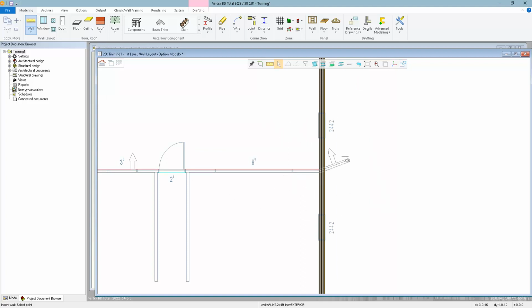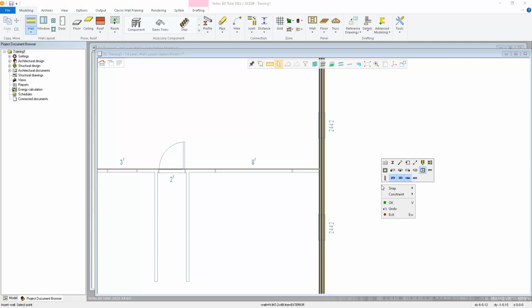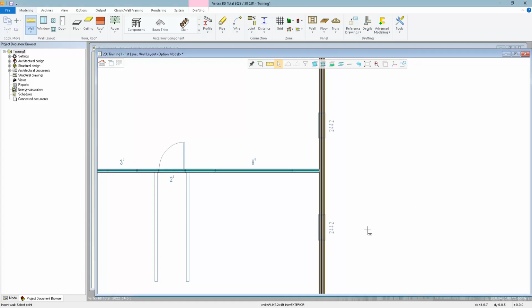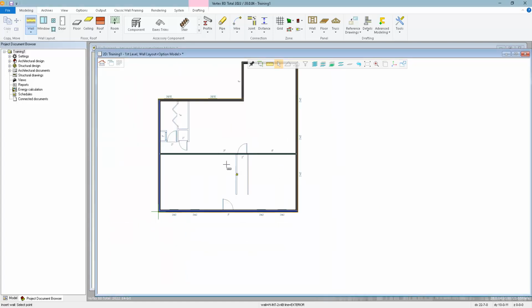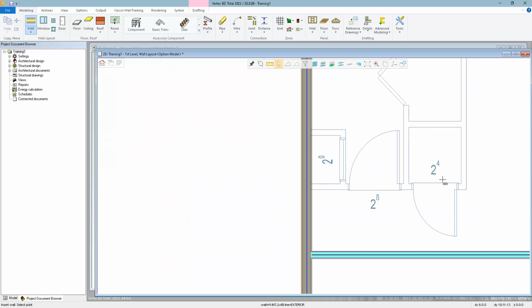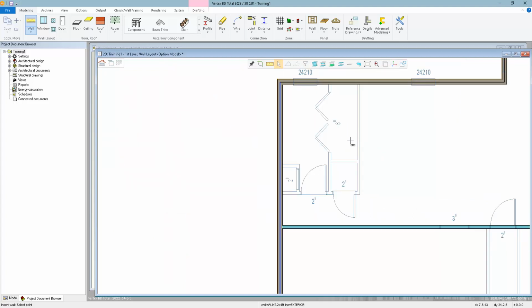And then it's waiting for me to select another point, but I'm done, so I'm going to hit confirm. So that is pressing down on the mouse wheel, or V on the keyboard, or I can right click and select OK, which shows you right there, the keyboard shortcut is V. And now I can continue and select additional walls. Here I'm going to go to interior non-bearing walls.